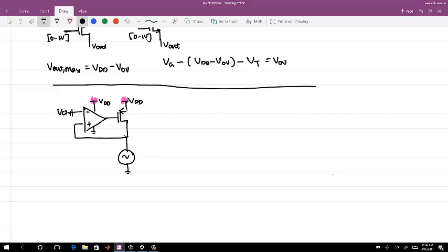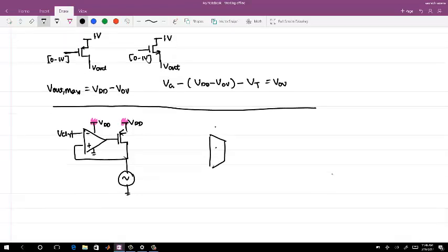So let me change this amplifier with the NMOS input, where we have effectively some GM block. Let me call that GMA, and the output resistance of that GMA is ROA. I'm fine writing that as an effective gain, so let me write it as RA for the amplifier. Then you have a capacitor at the output, which is CA.